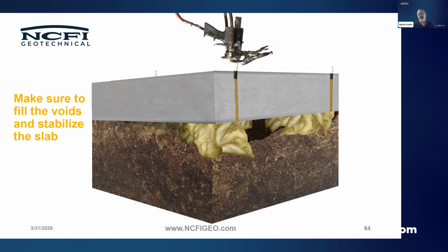What we don't want to do, though, is leave big voids in between the different injection locations. We want to make sure that we're filling that. Foam works by spreading the load. And so spreading the load here means that we don't have to have every single bit of concrete covered underneath, but that's our goal.